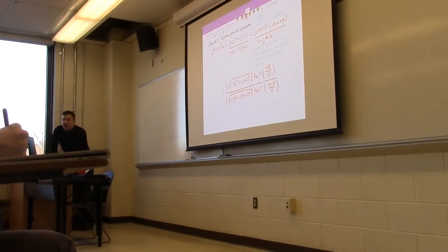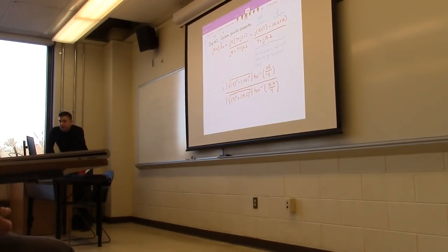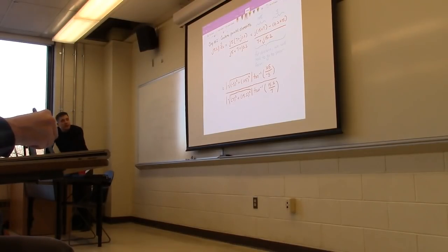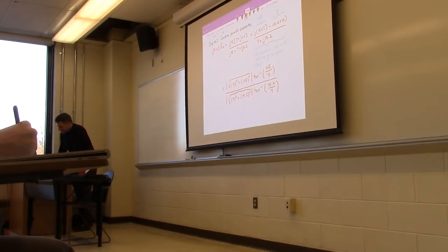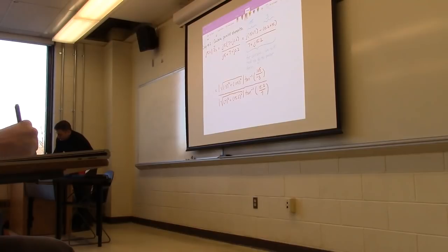Now, one thing that I always recommend when you're doing these inverse tangents is that you have to keep track of where you think the phasor is supposed to be, where the angle is supposed to be. Because the inverse tangent of -105 over 3 is the same as the inverse tangent of 105 over -3. The calculator doesn't know. So the way I like to do it is, I know that this has a negative real portion and a positive imaginary portion.